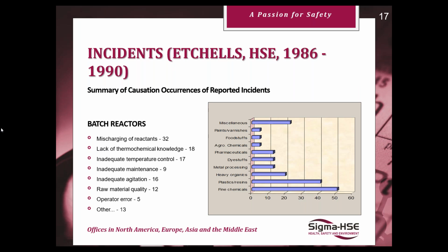Even for chemicals that aren't used in the chemical process, cleaning agents, there's been cases where mischarging large volumes of, I think it was 2 acid-base cleaning agents, nitric acid and the other containing isopropanol, actually resulted in the formation of isopropyl nitrate, which used to be used as a rocket propellant. So very explosive and really quite catastrophic.